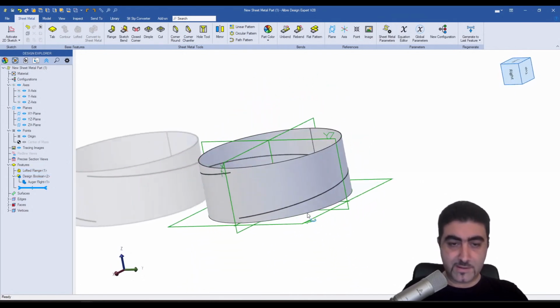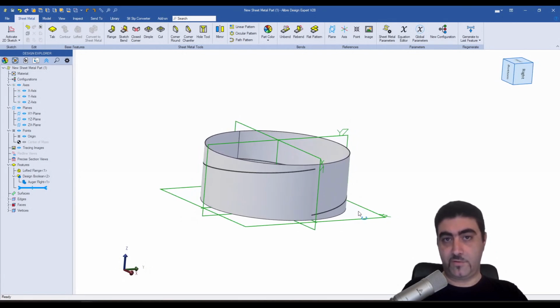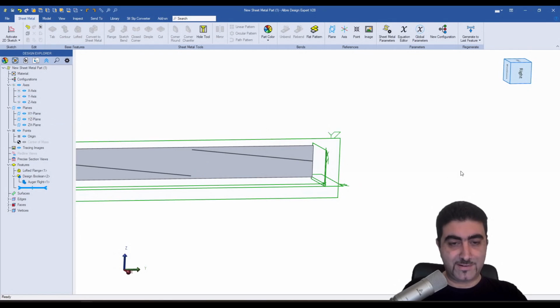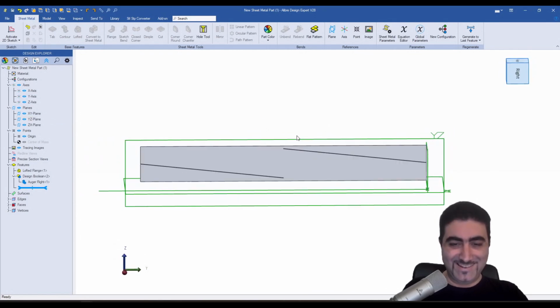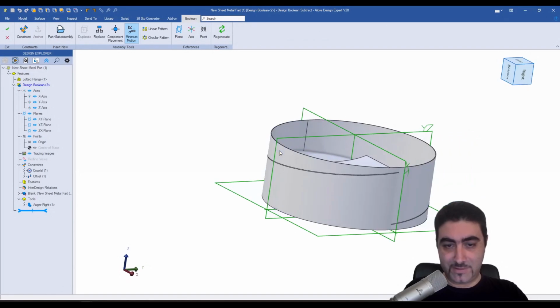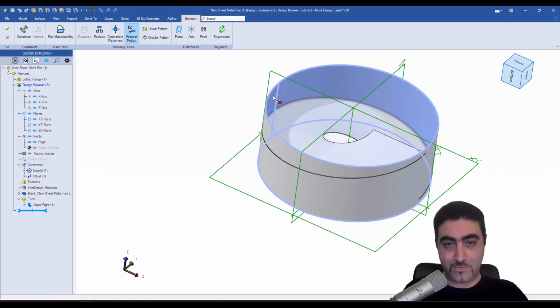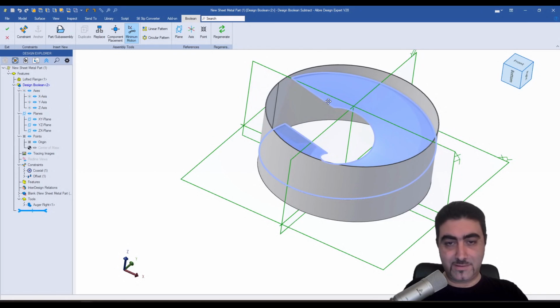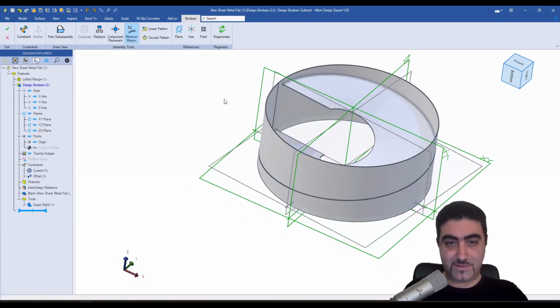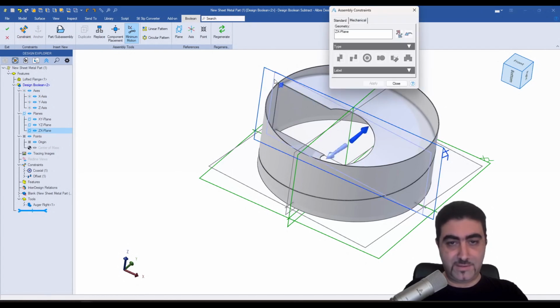So this is the trace of my auger flight. So when I make the flat pattern, okay, well, let's fix it. We can fix this. What we need to do is spin this around so the start of the auger meets the start. There you go. Let's get our reference plane going again and make these two.